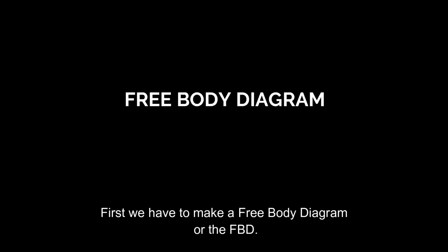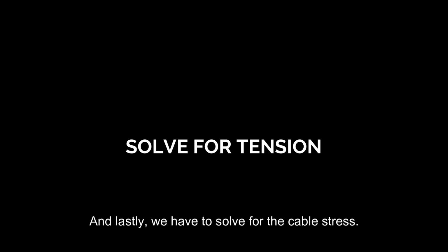So here are the steps in solving this problem. First, we have to make a free body diagram or the FBD. Second, we have to make summation of moments. Third, we have to solve for tension. And lastly, we have to solve for the cable stress.